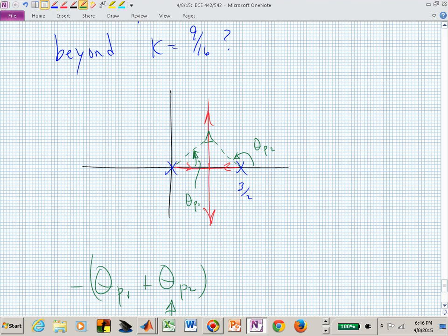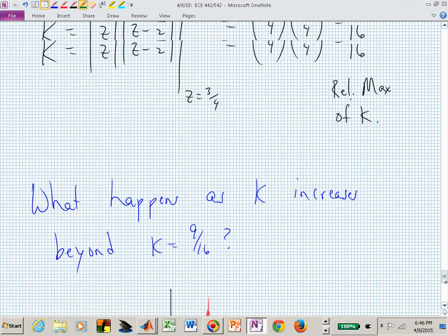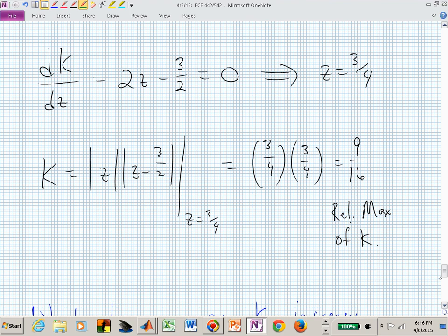So now you have a radius of 1 is the real part squared plus the imaginary part squared. You can solve for that imaginary part, and you know now the z location where you intersect the unit circle. You can use that z value, even though it's complex, you can plug it into this k and find the k to get you to that point. And you'll find, I hope, that that's 3.